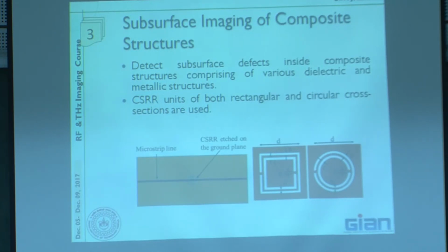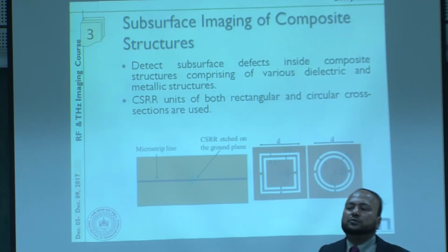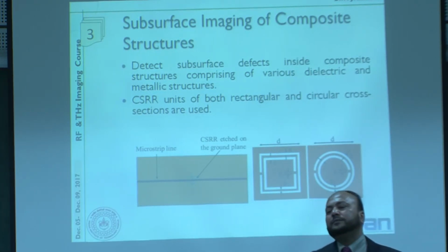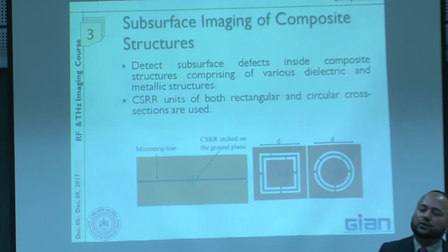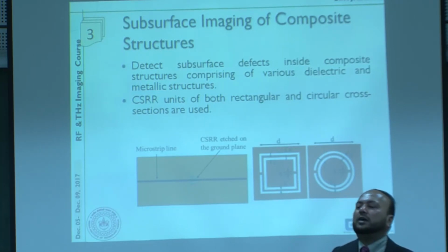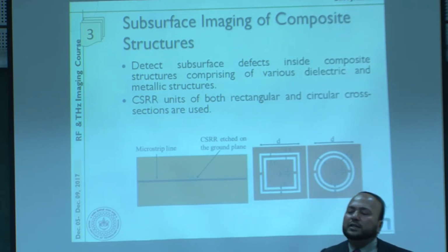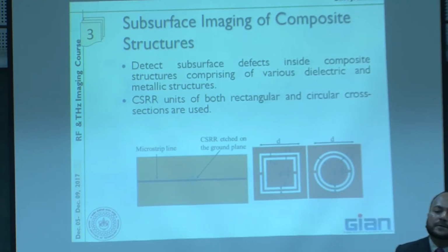Only then can you tell, because let's say you go from permittivity 1 to 2 and the frequency shift is from 1 gigahertz to 1.0001 gigahertz. You don't know whether this is an anomaly or the actual value. However, if you have another system where, going from permittivity 1 to 2, you detect a shift in frequency from, let's say, 1 gigahertz to 1.1 gigahertz, that's perfect. You have around a 100 megahertz shift. That means you have more shift. So ideally, the simple thing is that for a unit change in permittivity, you want to obtain the maximum shift in the resonance frequency.